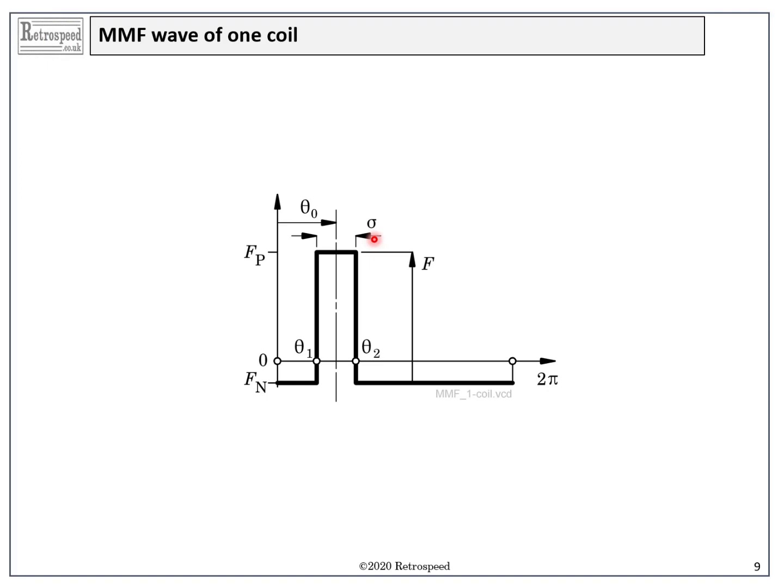But we ignore the even harmonics on the assumption that the winding is going to be balanced between its north and south poles. But we should take note of the fact that if this balance is not perfect, the winding will have even order MMF harmonics, and it will cause even order flux harmonics, and these will tend to flow in return paths which include the shaft and bearings, and which will be a source of trouble, including noise.